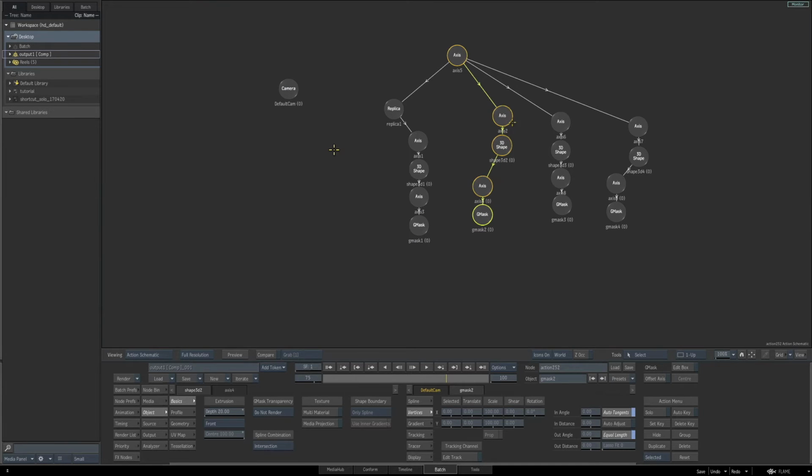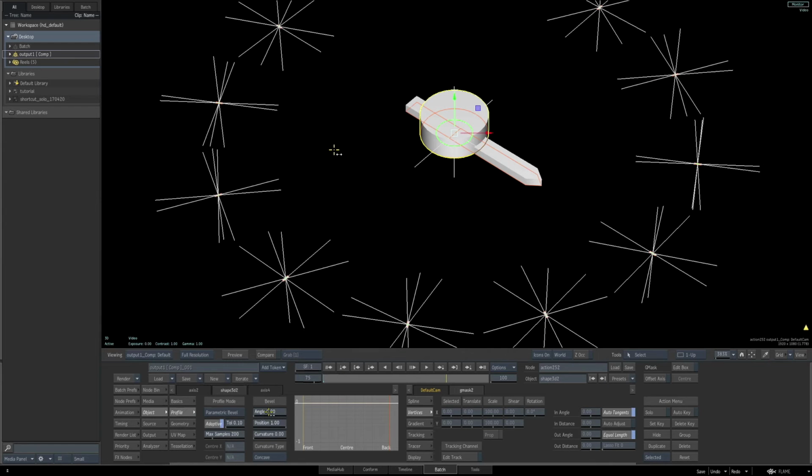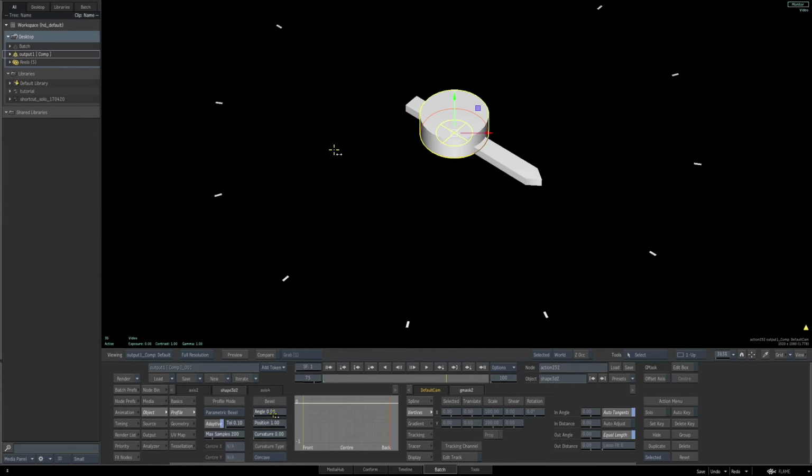Make sure the 3D shape is what is highlighted and selected, which it is. And then I'll go to the profile options. Let's hit F4 once again to go back to the end result so we can see it happening as we make the adjustments. Once again, I'll hit the I key to go back to just selected for our icons. And coming down to the parameters, I'll adjust the curvature to 1, and then we'll start adjusting our angle.